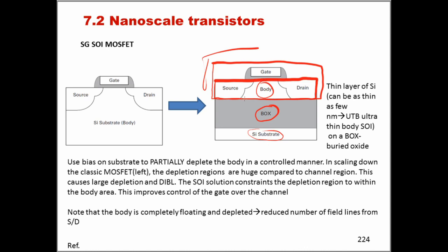We are also exploiting here electrostatic phenomena. If you remember, one of the big problems when we shrink the transistor is the fact that the depletion areas around the drain and the source contacts extend so much into the channel area that they cause drain-induced barrier lowering and all the other effects we've discussed. But here, because the body is so confined in space, electrostatics is in a way helping in keeping these depletion regions reduced.